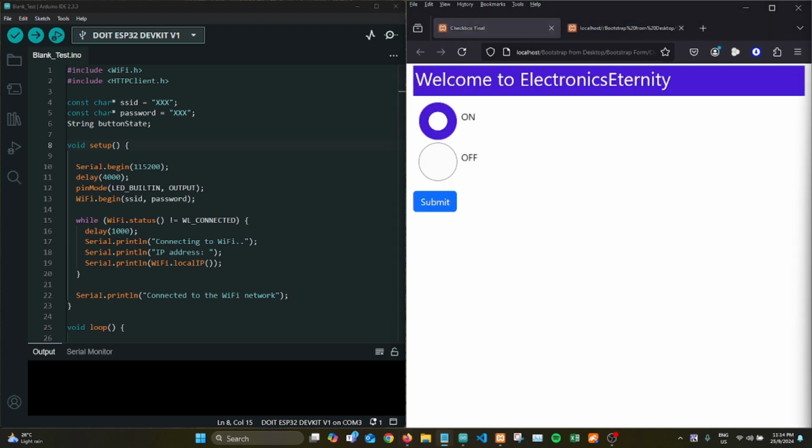For the sake of simplicity, my endpoint device is simply a built-in LED from ESP32. But then again, you can use any endpoint devices that you like. For an example, your endpoint devices can be a servo motor or a DC motor, switch, LED, or even relays to control higher voltage devices such as fans, wall lamp, shutter, or just about any devices that you desire.